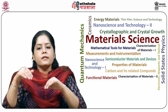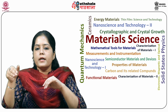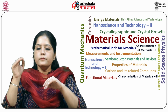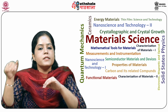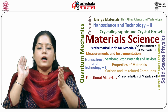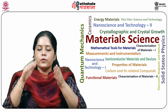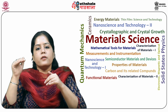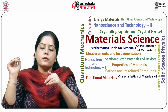V_D minus 2a epsilon s by q N_D multiplied by V_bi minus V_G minus 2 by 3 multiplied by 2a epsilon s by q N_D multiplied by V_bi minus V_G plus V_D the whole to the power 3 by 2 plus 2 by 3 multiplied by 2a epsilon s divided by q N_D multiplied by V_bi minus V_G to the power 3 by 2, square bracket close.